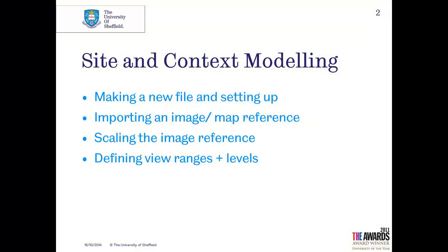So in this video we are going to cover a few initial steps and preparation tasks really to get us underway modeling our site in Revit. So this is what we're going to cover: making a new file and setting up, importing an image or a map reference, scaling the image reference, and defining view ranges and levels. So this is really the initial setup tasks that we need to do just before we can start